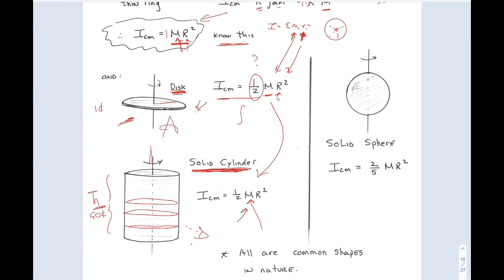If I have one penny, I have the mass of a penny. If I have a stack of pennies, now I'm going to have a larger mass. So that letter h is a height that's parallel to the axis of rotation. It's along that direction, and only things that go outward from the axis of rotation contribute to the moment of inertia. So the h isn't being ignored, it actually shows up in the mass. The more height you have, the bigger mass you would have.